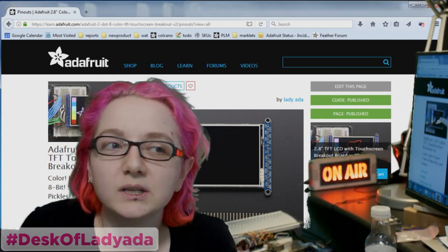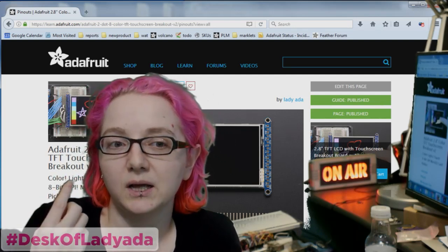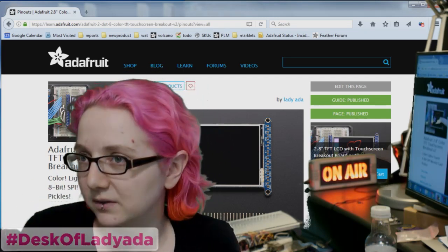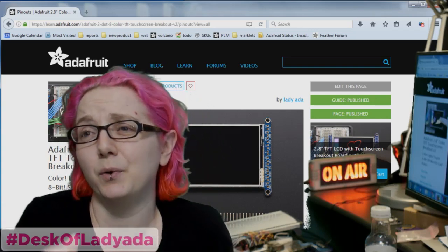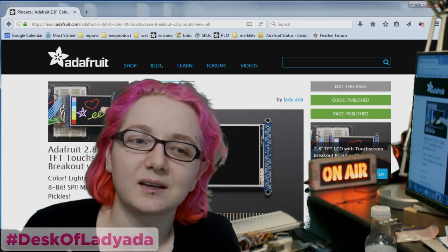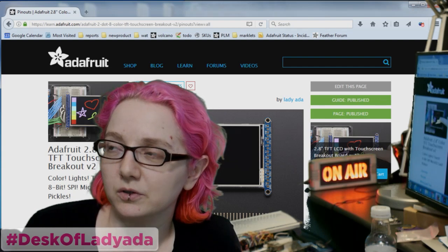Usually, with capacitive touch, the cheap controllers can do 1 point, and then some of them can do 2 or 3 or 4, and then the really nice ones can do 10. But honestly, people don't tend to use more than 2 or maybe 3 points. You pinch and zoom, kind of the only thing. I'm a little iffy on whether 10 point is required, but some capacitive controllers use 10 point.